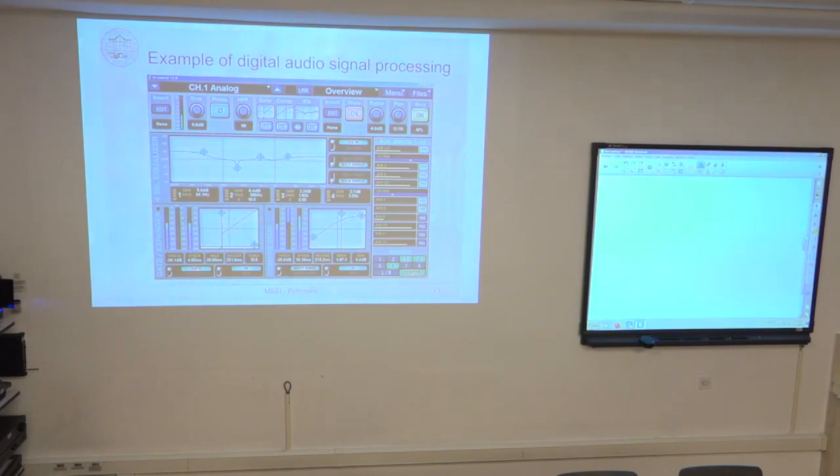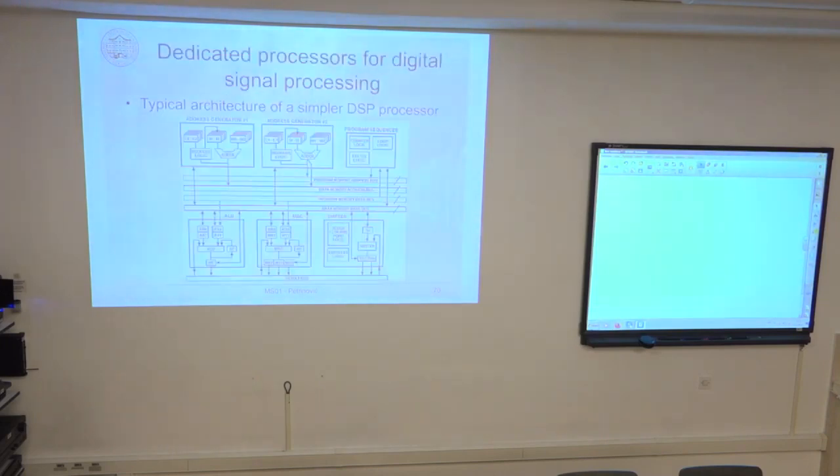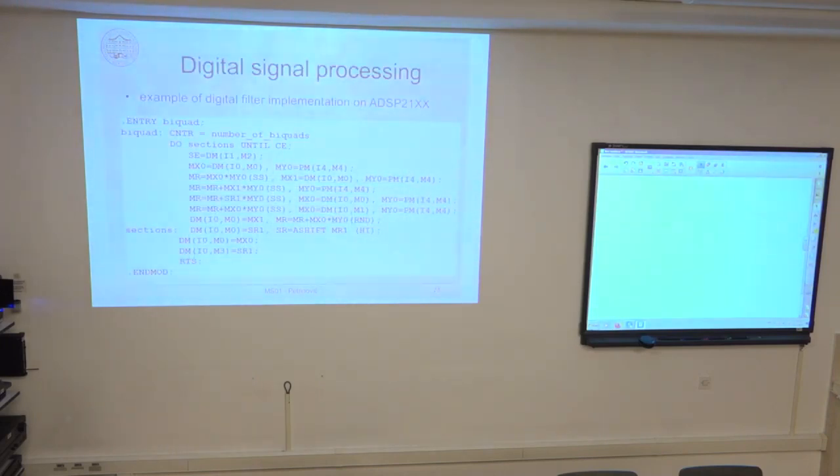And in these 25 microseconds, you can easily perform processing of this kind. For example, if your CPU runs at only 10 MIPS, you could do 250 assembly instructions between two samples. And you have here maybe 8 instructions times whatever number of different sections, much less than these 250 instructions. You can do this in real time.